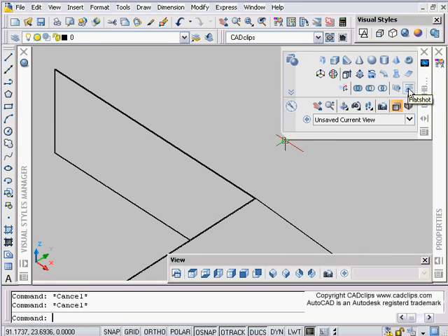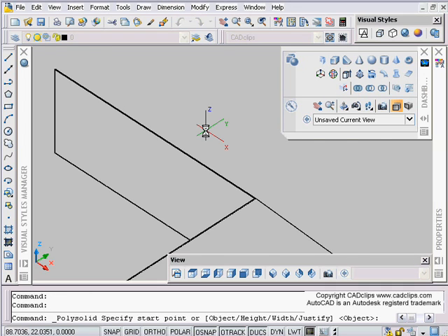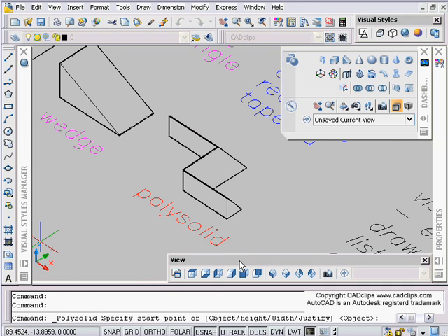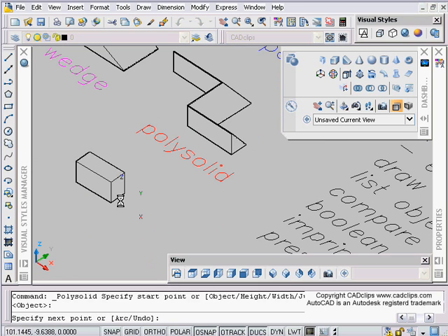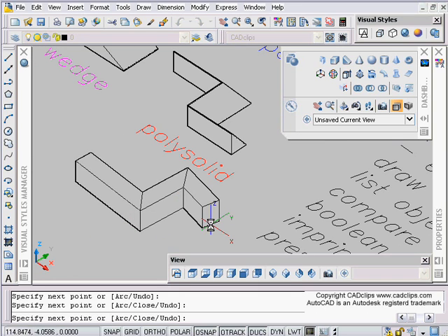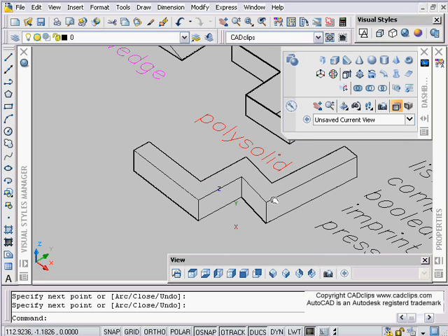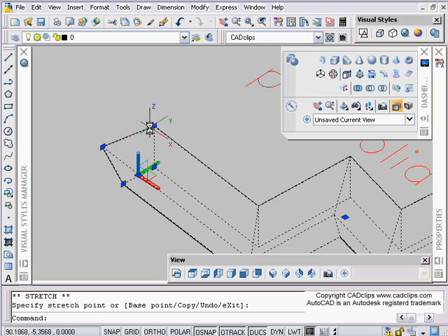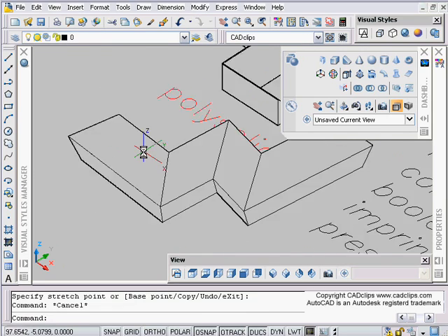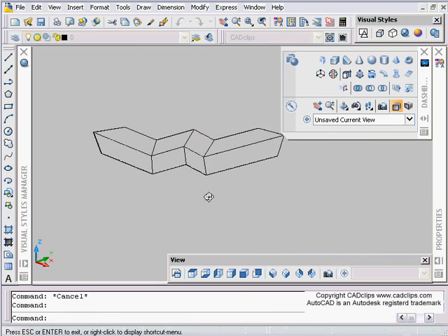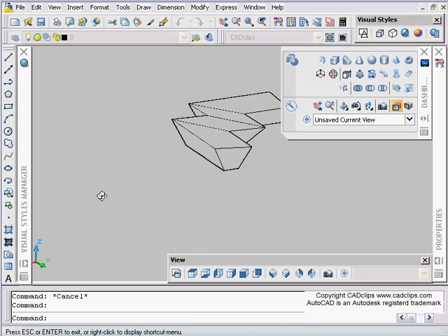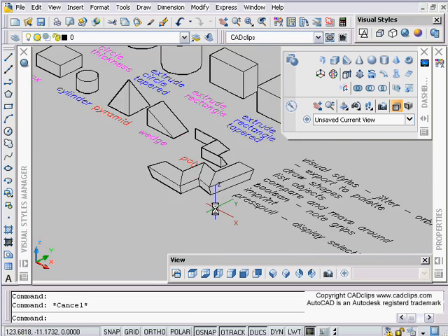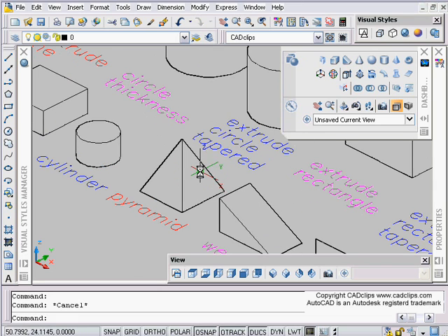We can go in and draw a new polysolid by going to, where's my polysolid command? And there it is right there, polysolid. We can say start, and we can set the width, but I think I've already got a decent width in there, so polysolid's probably one of the coolest. And remember, we have to hit an enter, not an escape on that. And then with that polysolid, we can take those grips. And using our ortho, you can do all kinds of neat stuff like that. Shift middle mouse button after we grab it. Start to use some of our Boolean operations.